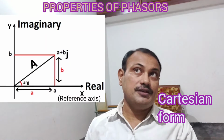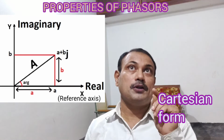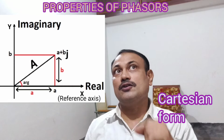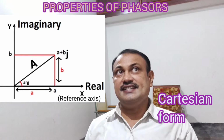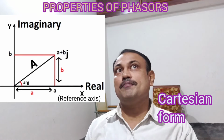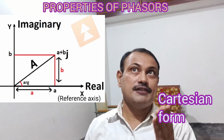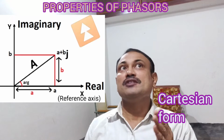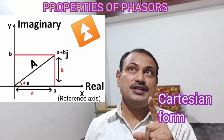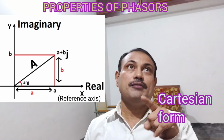In Cartesian form, if you write the phasor as capital A equal to small a plus j times b, with small a as the phasor component along the positive x-axis, which is the reference axis here, and small b as the phasor component along the positive y-axis, where we can reach from the reference axis by moving 90 degrees in an anti-clockwise manner. If we are considering anti-clockwise, it is 90 degrees, or 270 degrees if we are moving clockwise.